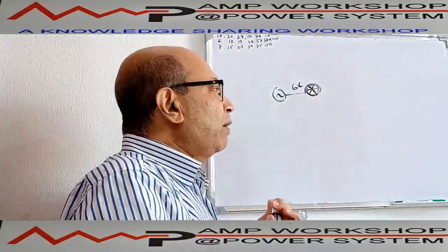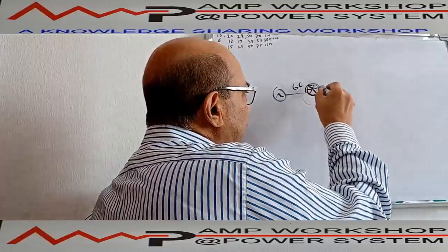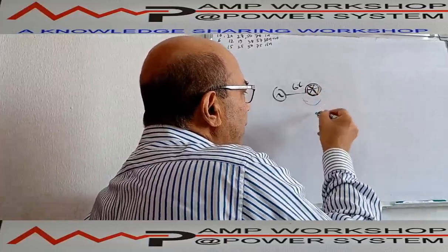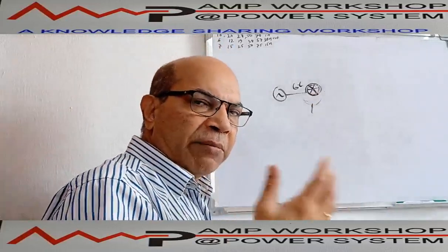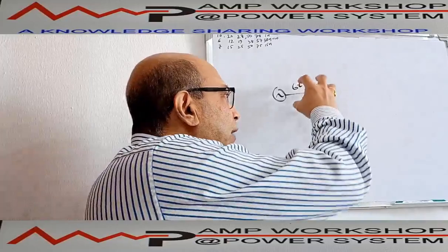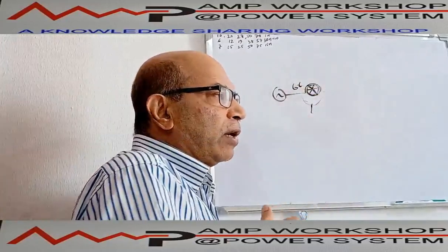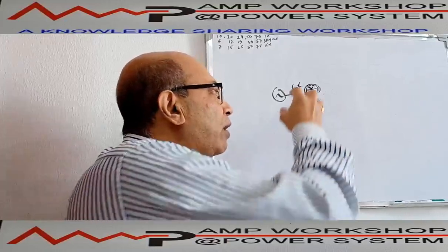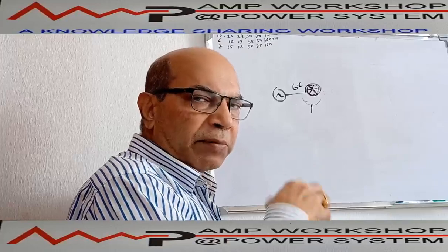That means we have to cover this conductor with some material on whose surface voltage will be zero. So if anybody touches this cable, nothing will happen. There is no damage and a life accident will not be there. So that means some insulating material is to be covered over the conductor, so the conductor voltage will not come to the surface of the cable or surface of the device.